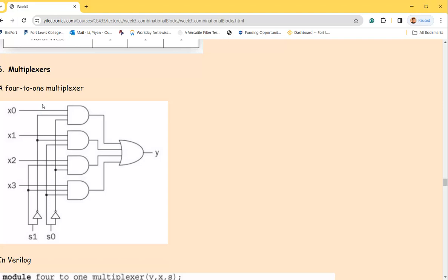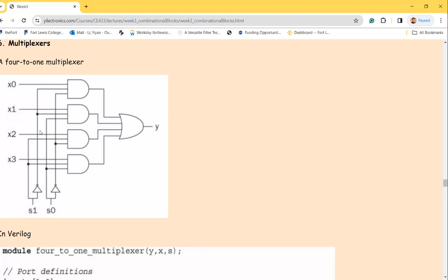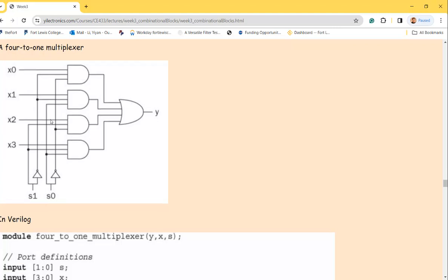But for combinational logic, I think data flow is easier because the one logic expression is very similar to just writing in C++. For example, if you can design or draw the logic gates on paper, you can definitely write down or type the data flow Verilog code easily. It's just a few lines of code.